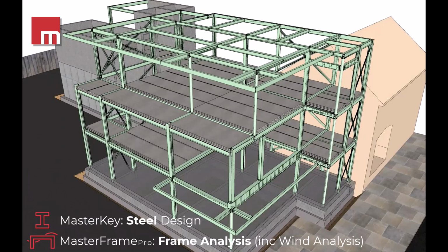It is a common construction type in Ireland, so there are plenty of locally skilled contractors and fabricators to facilitate this type of construction, and the site wasn't in a really restricted location, so deliveries for longer members wasn't a limitation. The lateral stability system was kept in steel as well, as there was no added advantage for specifying concrete shear walls, although that can also be designed within the concrete slab and wall designer. And I should also mention wind loads were applied with MasterFrame as well, using the wind analysis module.